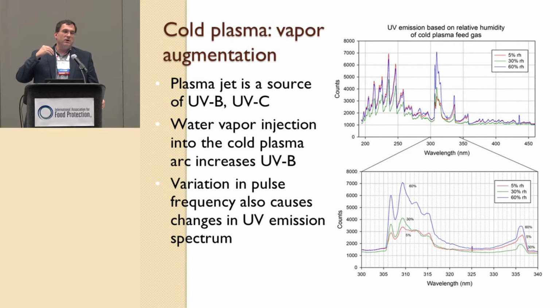So you might say, well, my system uses air. Well, if you're not controlling the humidity of the feed gas that's going in, then you might be getting a very different kind of reaction product than you're expecting. And it can lead to variations in your results, which might make it work on Tuesday but not on Thursday, which is a headache. But it also has some serious impact in terms of your process validation later on if you're trying to run this for 1,000 hours on a production line.